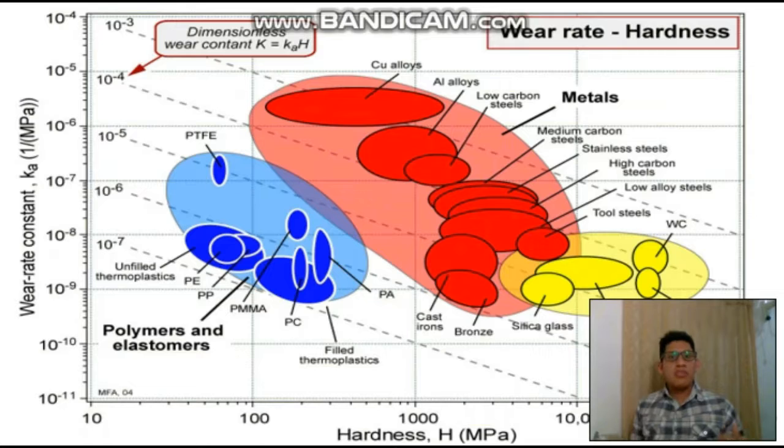The wear rate is measured as volume in cubic meters over the force in Newtons times distance in meters, which results in 1 over megapascals. It should be mentioned that the wear rate is not strictly constant, but remains constant after a period of transition. For the same purpose, material development is necessary to have some universal quantitative parameter for wear. In many cases, it's more relevant to compare the wear properties than only the friction properties.